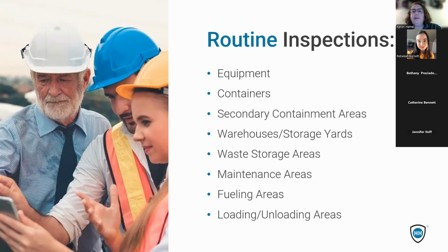And the inspections can be simple. They can be simply looking at the equipment and making sure that you don't see a visible leak or spill around it. They could be an inspection that involves a little bit more. Maybe you are looking at seals quarterly, or you're looking at valve fittings, or you're checking and replacing things.